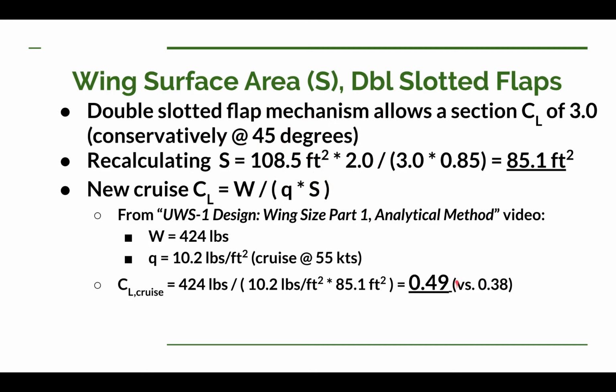That actually is a very nice result, because you may remember in our airfoil selection video, we were having a hard time getting an airfoil that would have low drag down to our lift coefficient of 0.38. Well, if we increase it to 0.49, now it's much easier, because most of them did have fairly low drag up around the 0.5 area. So that's a great thing for us.